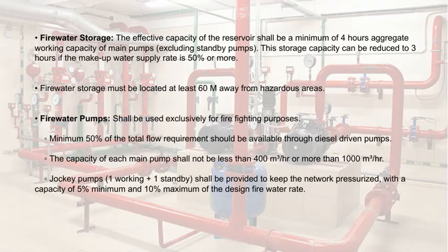Now let's talk about fire-water storage. The key point here is that the reservoir should have a minimum effective capacity of enough water to sustain 4 hours of operation, based on the main pump's working capacity. However, if the makeup water supply rate is at least 50%, this capacity can be reduced to 3 hours. It's also critical to position the firewater storage at least 60 meters away from any hazardous areas to ensure safety